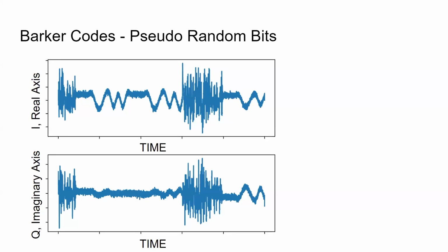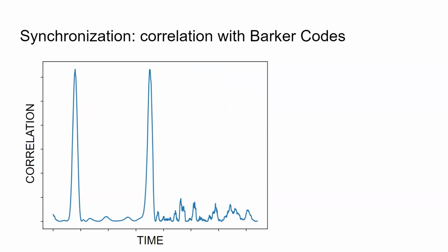A Barker code is a kind of random signal, but the thing is our receiver and transmitter both know what the signal is. So when we receive our code, we can take our Barker code and compare it along the whole thing and find where it is. You can see that might be the Barker code, for example. How it's actually done is a mathematical function called correlation.